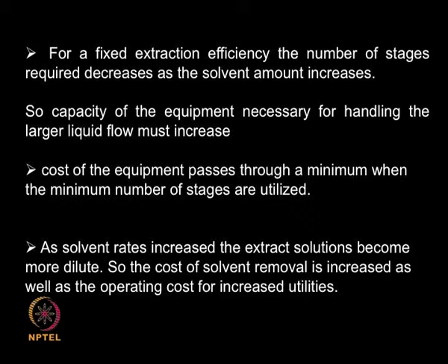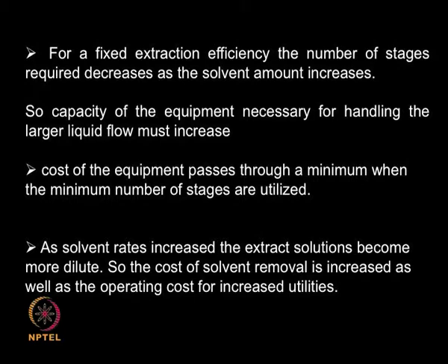Is it good to have a small number of stages which are very large, or a larger number of stages which are very small? Because this type of contradictory forces is at work, the cost of the equipment passes through a minimum. That means there will be an optimum number of stages that are utilized.